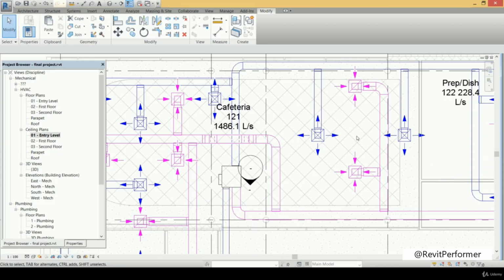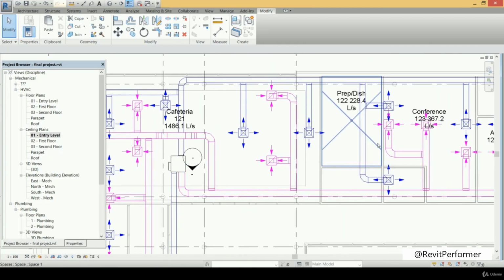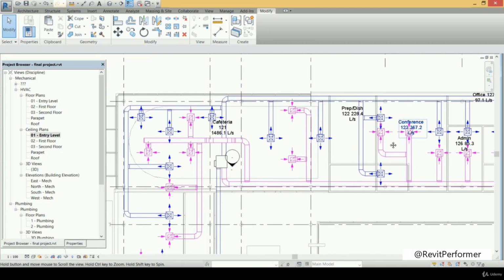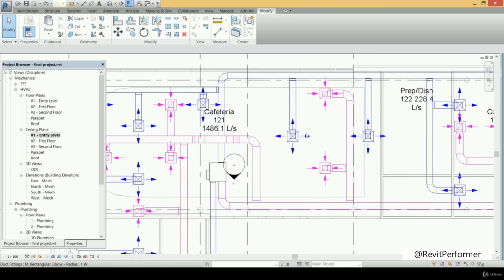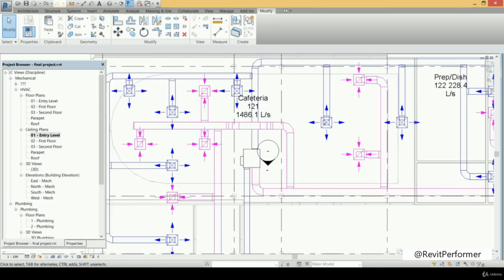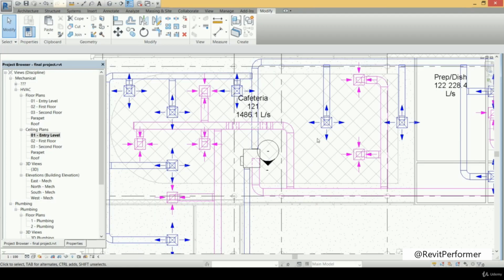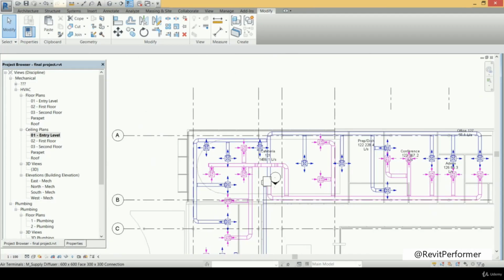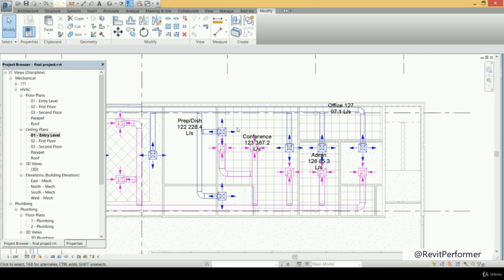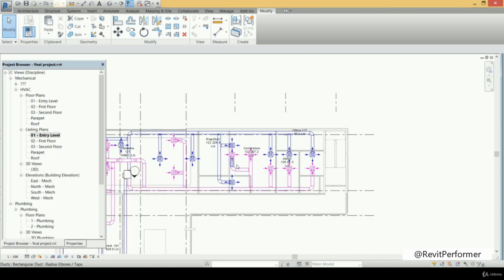So it's suspended ceiling square slabs go with a declination angle. As you see here, it goes with that angle, while the slabs for the other rows are going vertically. So we will align the diffusers, or that air system, with those declined square slabs, not to be vertical as the traditional design for the other spaces that we have.